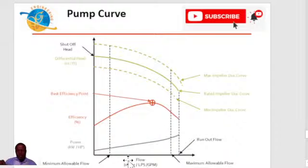So the efficiency of a centrifugal pump is lower in shut-off condition, and at the same time lower in run-out regions. That is why it is always advised to run your pump very close to the best efficiency point flow rate.